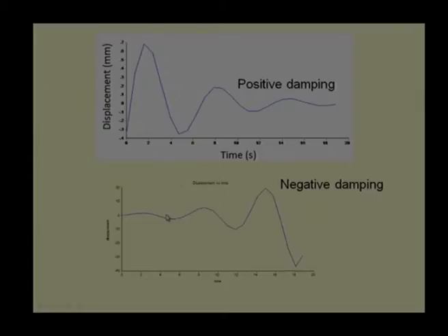Well, coming to negative damping, even though it starts from 0, it reaches some maximum value, then in the next cycle this value increases, and subsequently keeps on increasing till a final knock between the components occurs, or impact between two components, or shock between two components occurs, which will make a lot of noise, reduce the life of the component and may cause fracture of the component.